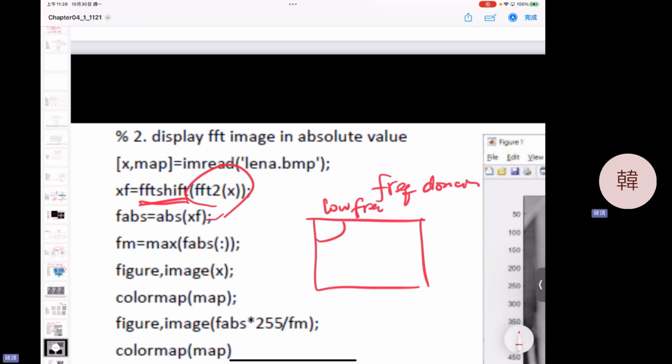We told you it repeats in 2 pi in N points. Mathematically it's 2 pi, but depending on how many points of resolution you did, it repeats M by N here. So the highest one, because it repeats in 2 pi, the high frequency part should be here. This is symmetric, because we have this repeated signal there.